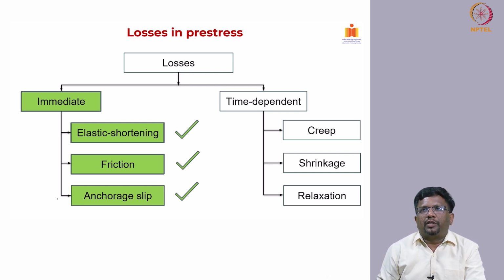In this lecture, we are going to talk about time dependent losses. And for time dependent losses, three important phenomena are there: creep of concrete, shrinkage of concrete, and relaxation of steel. All of them also induce losses in pre-stress.